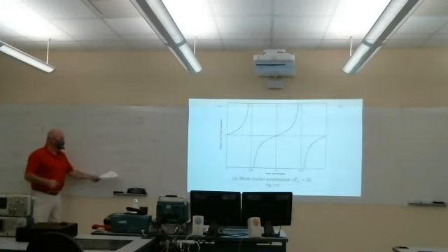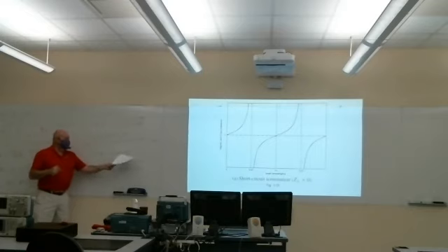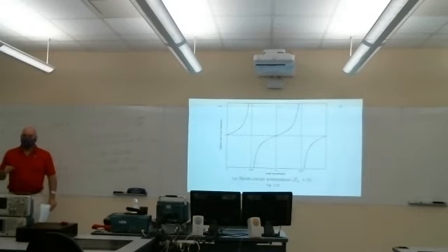Notice that this is an entirely reactive impedance. There's no real part; it doesn't look like a resistance. Over a range of L, this looks inductive, but tangent can be either positive or negative, right? The impedance of an inductor is plus jX, j omega L.